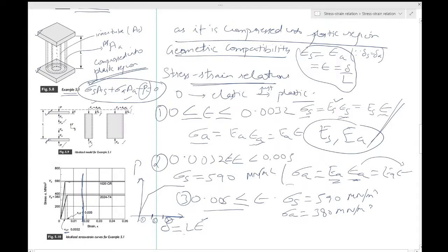So it is increasing from 0, the deformation of this entire assembly, and going into this non-strain hardening plasticity. So this is how you can study the plasticity of an entire assembly with the plasticity of the individual parts. Very useful. If you have one part which has failed, one is safe, how does the whole assembly behave? Most machines will have this challenge.